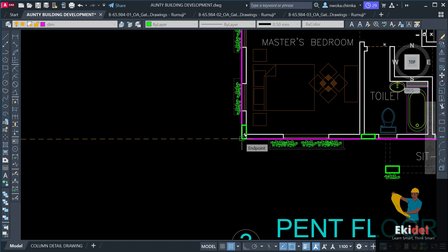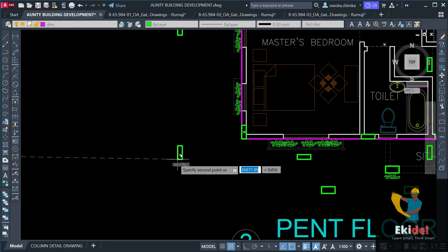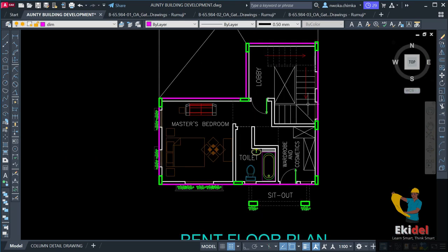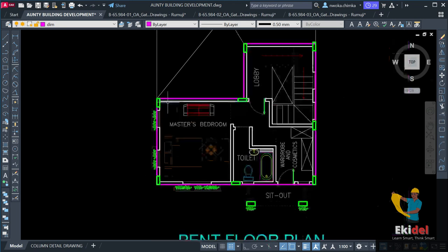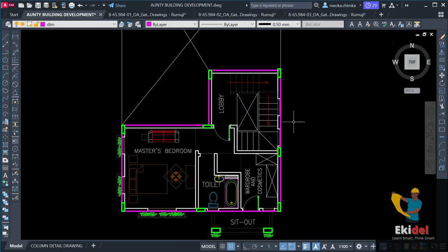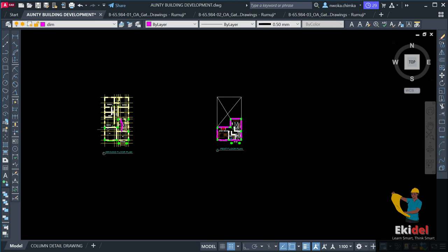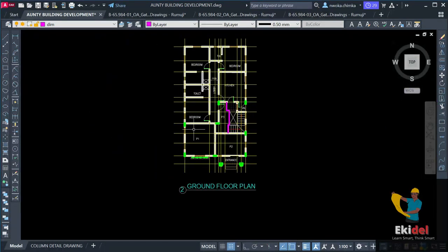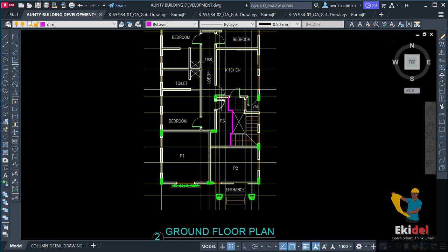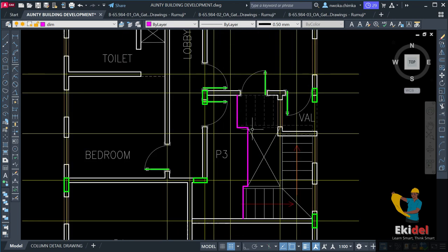Else, we will not know the columns that we're going to terminate at the slab and the ones that will continue down to the roof. So with this, you can now see that all the columns flush or are hidden inside the walls. So it's perfectly okay and sound. To now begin to move this building to Protastructure, to begin our full structural design in Protastructure, like I said before, when we get there, I'll show you how to suspend this slab on this area.